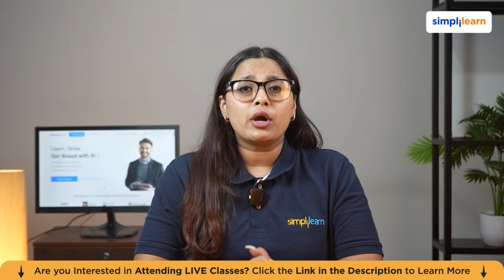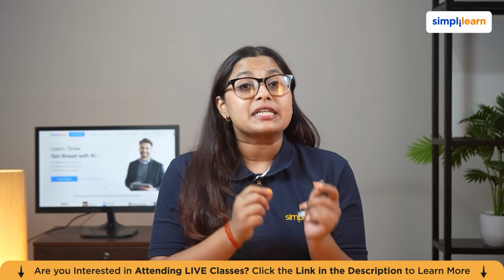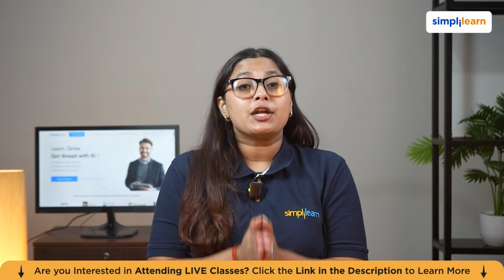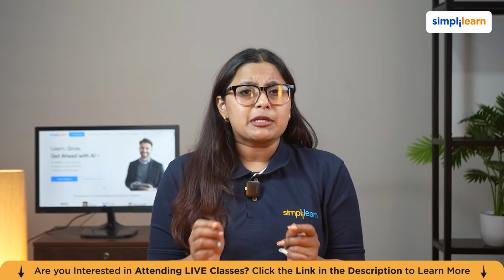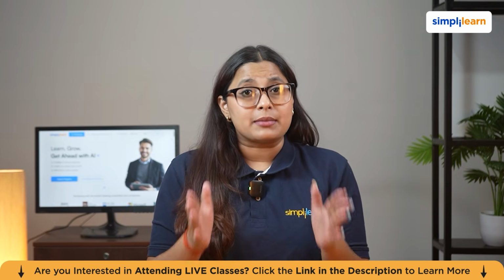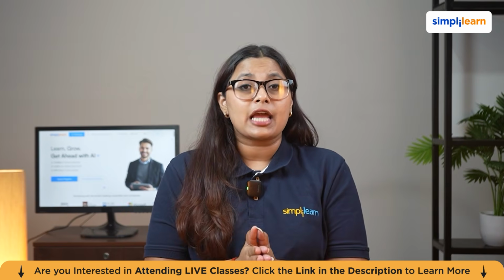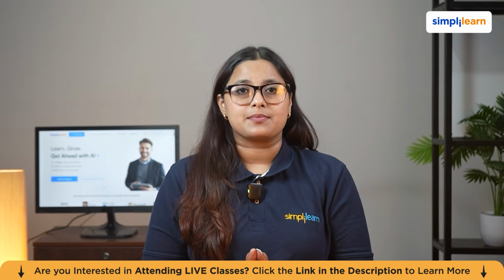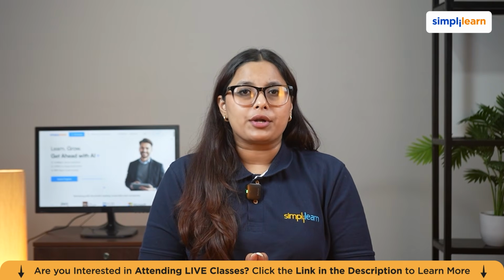In this module, we are going to solve the most common and most frustrating problem in construction scheduling: the same resource being needed in two places at the same time. In MS Project, this is called over-allocation. And it is not a sign that you made a mistake. It is what your schedule looks like before you have managed it. It is the software being honest about the real constraints. The question is, what do we do about it?